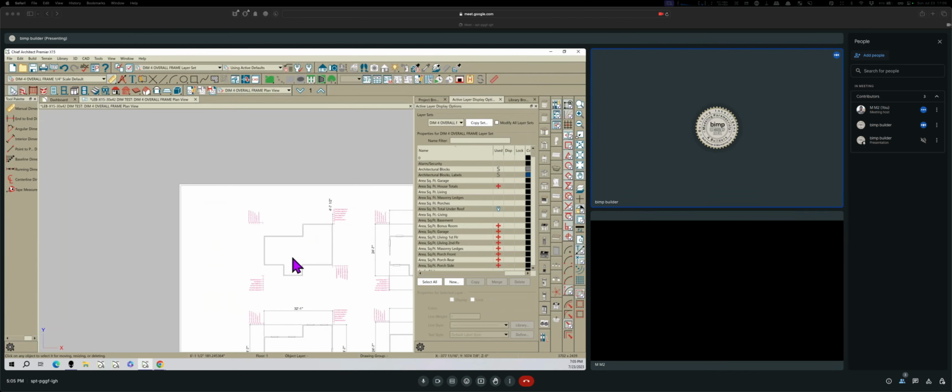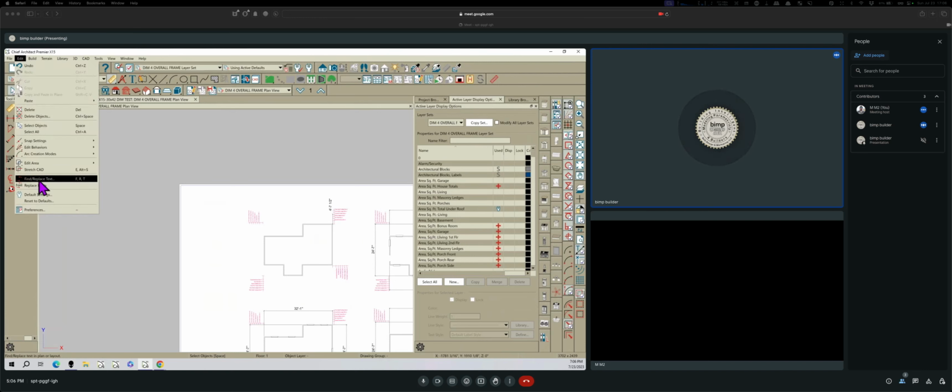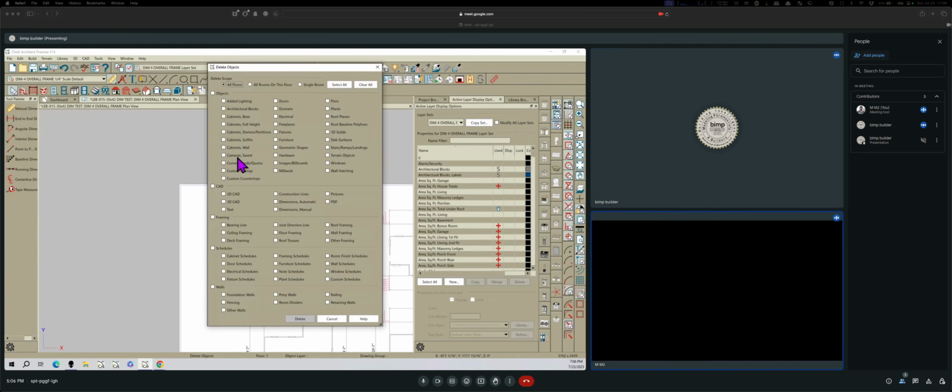Have you tried the edit, delete objects, and you can pick all the dimensions, and boom, in one time it's done? Okay, do edit. Go down to delete objects. Go up a little bit. Keep going up. It's delete objects, right underneath paste. Oh, yeah, I see it. And then from there, go to CAD, and inside CAD, dimensions. Just click on the dimensions automatic, the box right to the right of your mouse. Right there. Click that, hit OK, and every automatic dimension goes away.